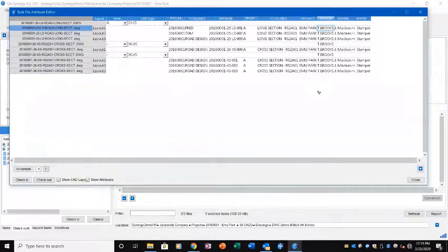If you're doing updates of CAD revisions, so you're revving all the drawings up, you can pick on a column. There's a button down the bottom here that says increment, and it will update it by 1 value. So whilst these are all the same, if they were a different mixture of A, B, C's, it would only step them up by 1 value. And that's all you've got to do.